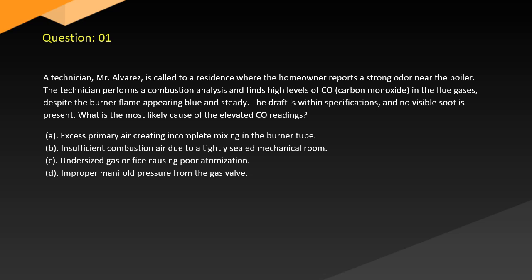A. Excess primary air creating incomplete mixing in the burner. B. Insufficient combustion air due to a tightly sealed mechanical room. C. Undersized gas orifice causing poor atomization. D. Improper manifold pressure from the gas valve.